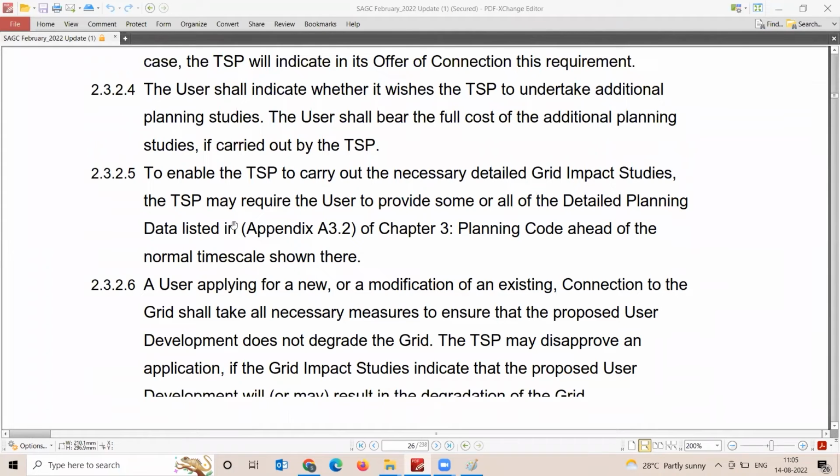Few countries specifically mention a few software packages, predominantly for load flow, short circuit, stability, LVRT, HVRT, and similar studies, for RMS studies. Most of the countries use PSSE, including India. Australia is probably the country which came up with requirements on PSCAD long back because of a constraint in their network. And nowadays, few countries have started following up on PSCAD too, though whether they are aware or not, they are asking. Countries like Oman go with DIgSILENT PowerFactory, and I am also a big fan of DIgSILENT PowerFactory personally.